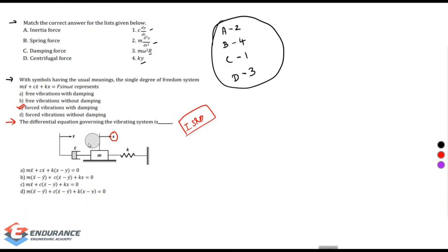Fine. But the problem was that a displacement y is given here. That displacement obviously is going to affect my damper. Damping force is going to get affected. But what is this y going to do with m? Nothing. The displacement y has no effect on this mass, nor on this spring. So simply x has effect on mass, damper and spring, and y has effect only on C.